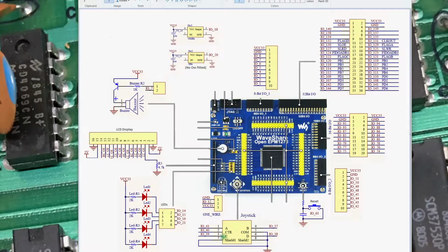There's the joystick we just looked at, where if I'm pushing on the joystick in some direction or straight down, one or more of these output pins will be pulled low. These are going to IO pins, or device pins 38, 39, 40, 41, and 37. So you can tell here again, these refer to the pins on the device. And you'll also find IO pin 41, 43, 39 right here. So you could also pick up the signals from this joystick on these pins to bring off to another device, or however you want to do this. Normally the joystick switches are open, so you could use these as general IO if you wanted to.